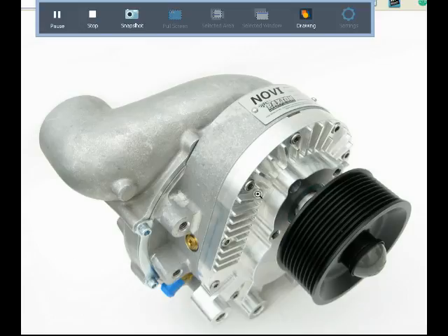So it depends what you're doing, but if you're going like for all altitudes up to maybe a mile or so, it's best to stick with the turbocharger, because you're taking advantage of that waste heat and you're not taking any power out of the engine that would normally be lost out of the exhaust.